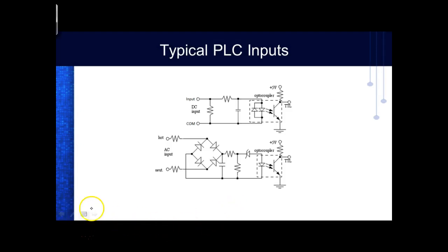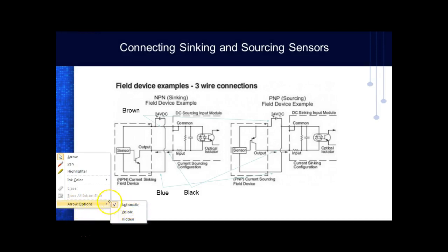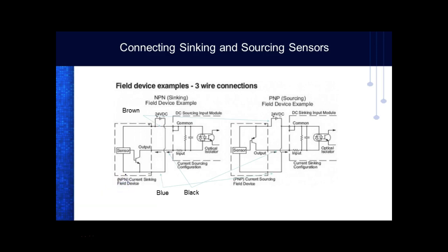Oh, there it is. So the way houses are set up, or the way 120 volt AC is set up, is we establish one lead that we refer to as hot. And then we have another lead that I call neutral. And then we have another lead that's referred to as ground. But what you find out is that back in your panel box, these two right here are wired together. And so neutral is our actual common for our AC. It's not our common for our circuit.